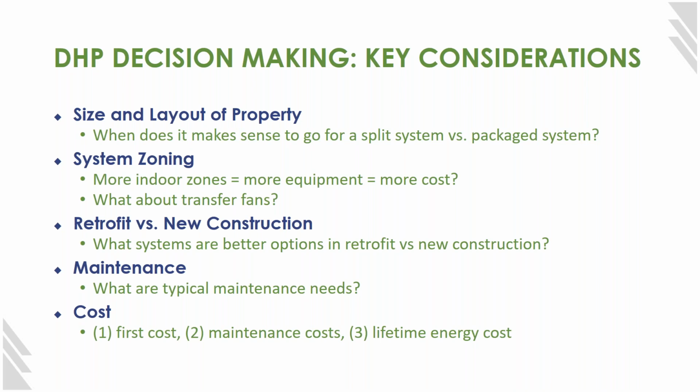In some cases, you might even be able to get away with having, for example, a package terminal heat pump in a living room, and that could deliver sufficient heating and cooling for the whole apartment. But you have to have some way to get that heating and cooling into the bedroom. That can be done with transfer fans. Are these ideal? No, but they can be a very low-cost way to effectively deliver the heating and cooling to the whole apartment with a single low-cost unit like a package terminal heat pump.